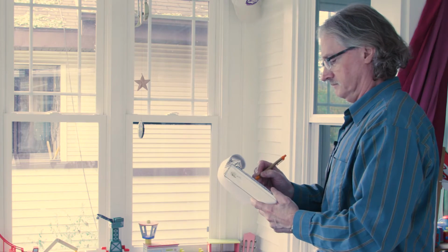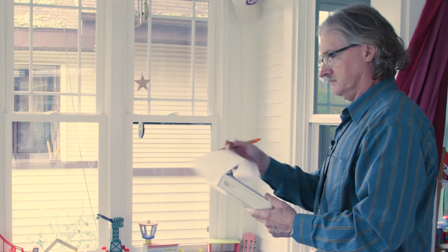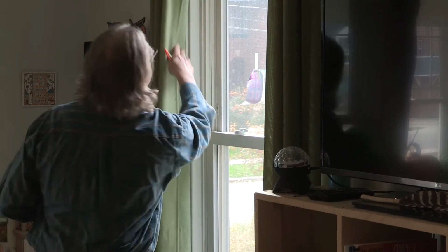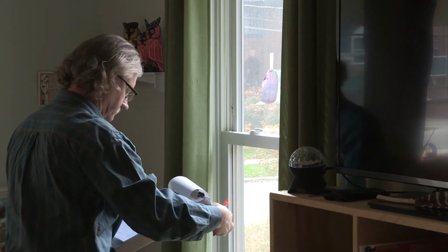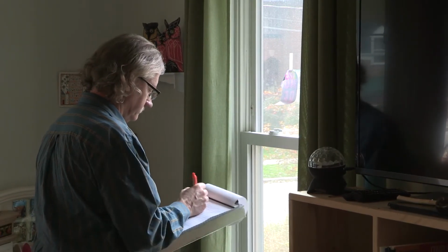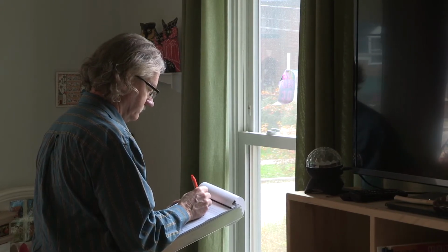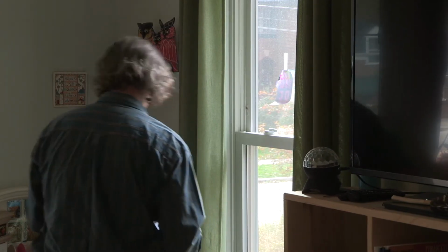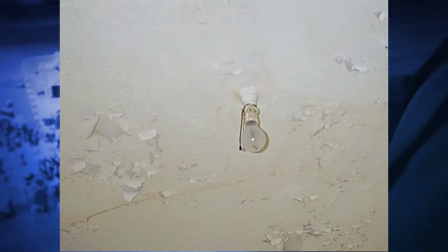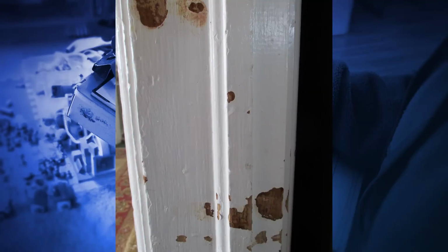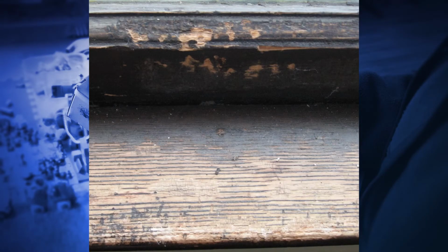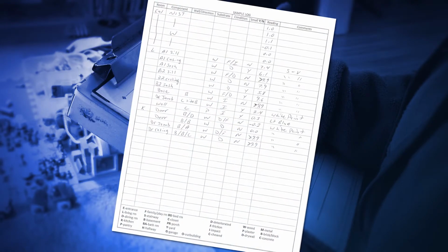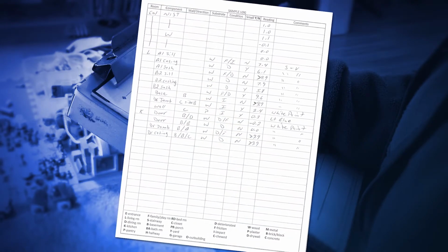Because a large number of readings may be taken in a thorough risk assessment, the location of each reading is not marked on the floor plan. Instead, for each XRF reading, record the room equivalent, component, room side, substrate, and the reading result in milligrams per square centimeter. While not required, it is helpful to also note the type of surface deterioration. For example, peeling paint, chipping paint, if it is an impact or friction surface, or if a painted surface shows evidence of chewing. HUD does not provide a form to record XRF readings, so it is recommended that you create your own method for recording this information in the field.